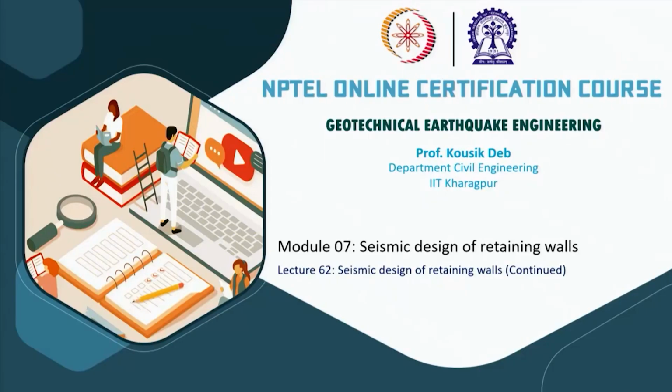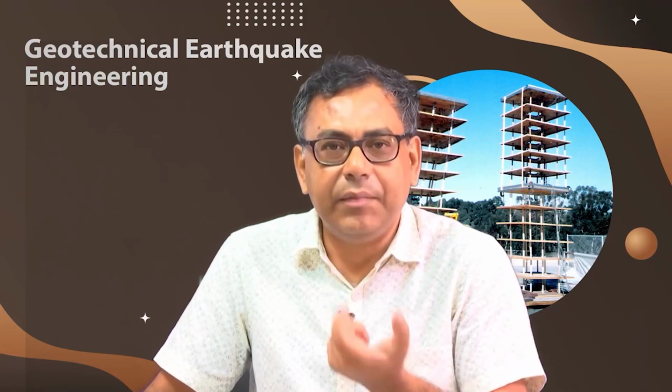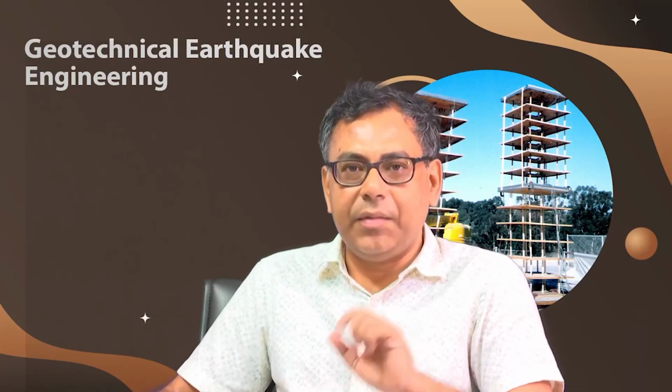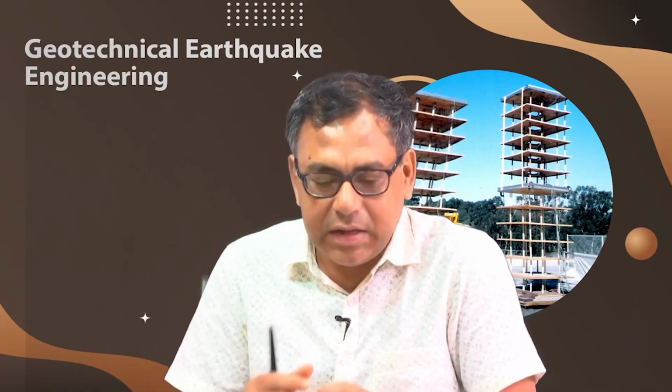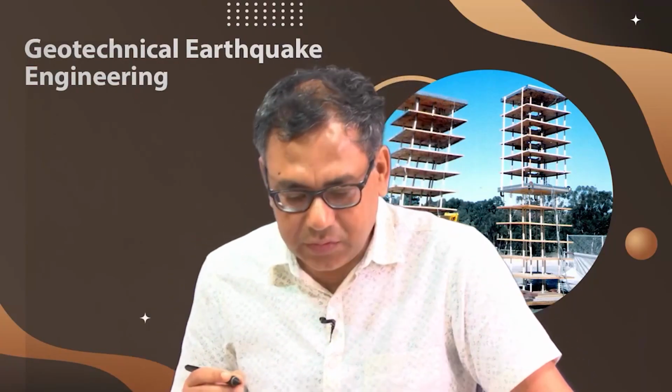And now, in today's class, first I will discuss the pseudo dynamic approach, because the previous lectures used the pseudo static approach, which, as I mentioned, has certain limitations. One is the time dependent behavior of the retaining wall, because your dynamic load is a time dependent loading. In this approach, the time dependent behavior is incorporated again in a simplified form. So, first we will take up the pseudo dynamic approach.